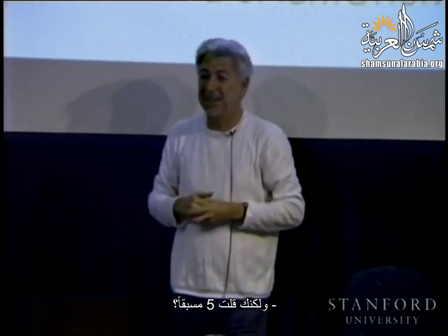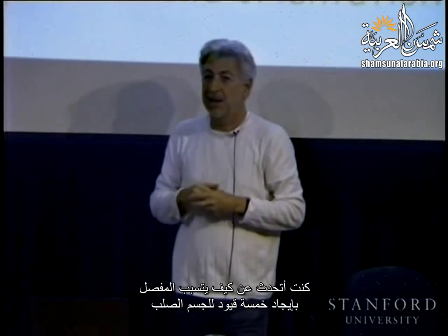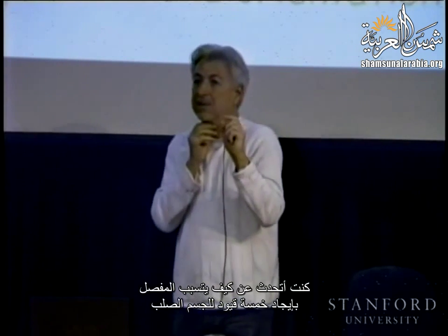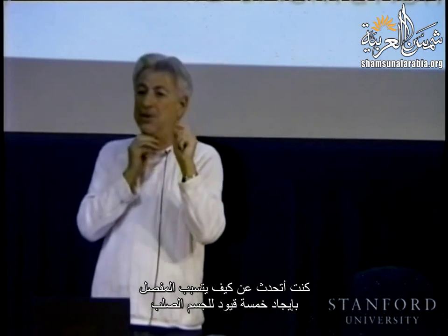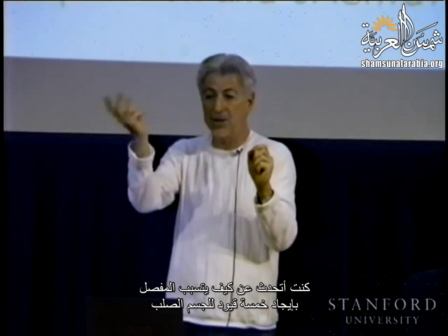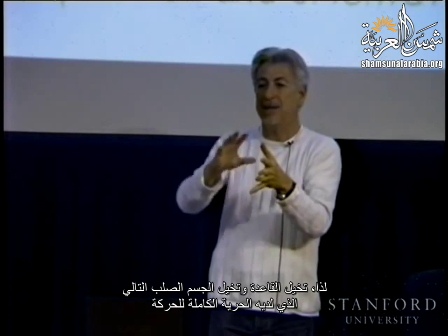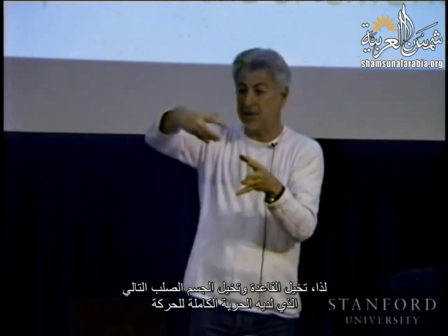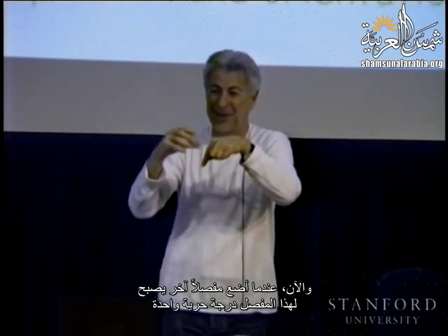Yes? Isn't that 6 parameters? Perfect. 6 parameters. Oh, I was talking about how a joint introduces 5 constraints on a rigid body. So imagine the base, imagine the next rigid body, it was completely free to move, and now I put a joint, and now it has only 1 degree of freedom left.